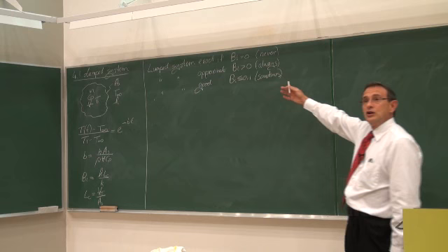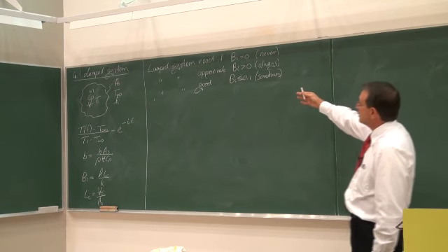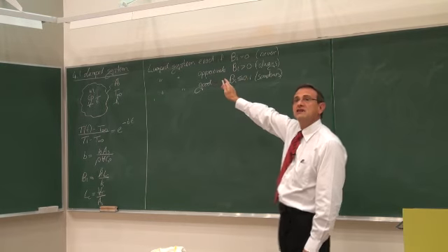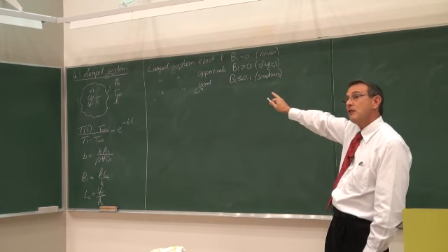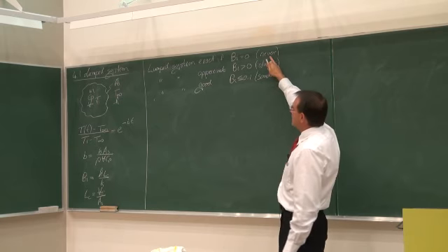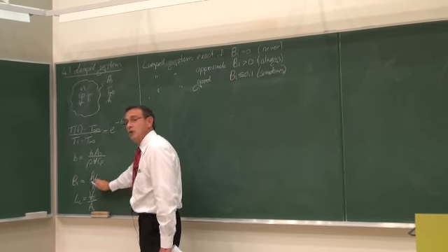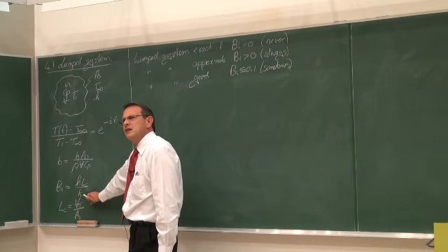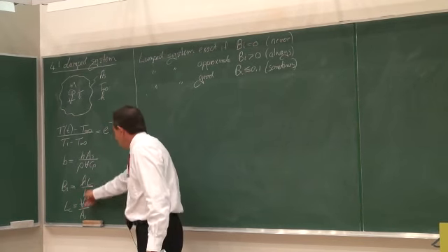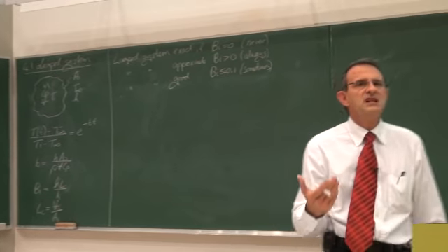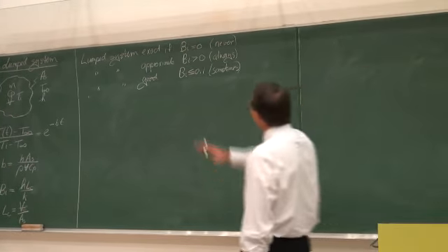In terms of using this criterion, we've said that if the Biot number is equal to 0, it would give us an exact solution of a lumped system. That never happens, because when we have physical things, it will never happen that any of those three terms can be 0. It can be close to 0, but it can never be exactly 0. So that is the first case.